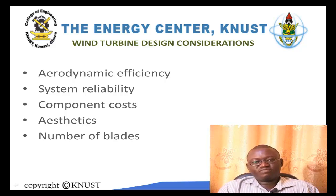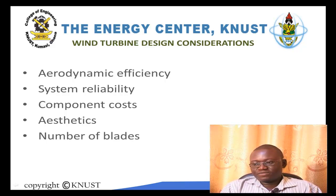And then the number of blades. This is a decision the designer has to make. So either 1 blade, 2, 3, 4, 5 blades, or even 10 blades. That is a decision the designer makes. But you need to bear in mind that the higher the number of blades that you go for, you create more inertia for the turbine. More inertia also makes it difficult for the turbine to begin rotation, or to respond to fluctuations in the wind. It makes them heavier also, so you have more stress imposed on the tower and all that. So all those things are things you need to look at in order to optimize the parameters.